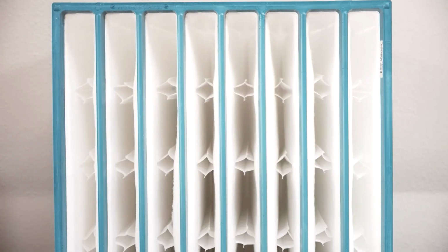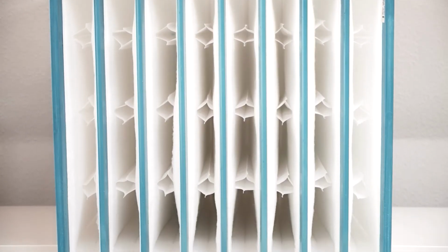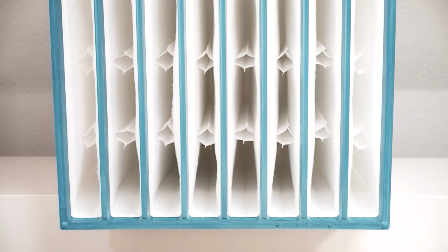Nevertheless, the first version of this standard was still very much oriented to the former European standard EN 779, which has been withdrawn in the meantime. Therefore, there was a need to write a modern standard that incorporates the latest state of the art. For the first time, the new standard also implements a procedure to assess the dust holding capacity of EPA and HEPA filters.